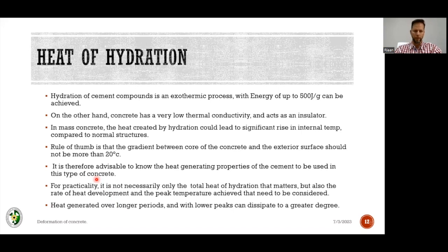That's what they wanted at 90 days. They embarked on a rigorous testing regime with the cement supplier, and they eventually sat with the maximum fly ash extension on this concrete, but they were still gaining too much strength over 90 days. They were sitting at about 28 MPa. So they really wanted to bring that down.